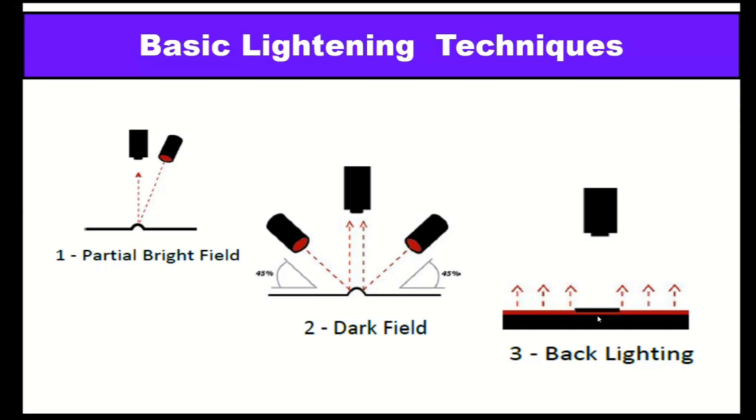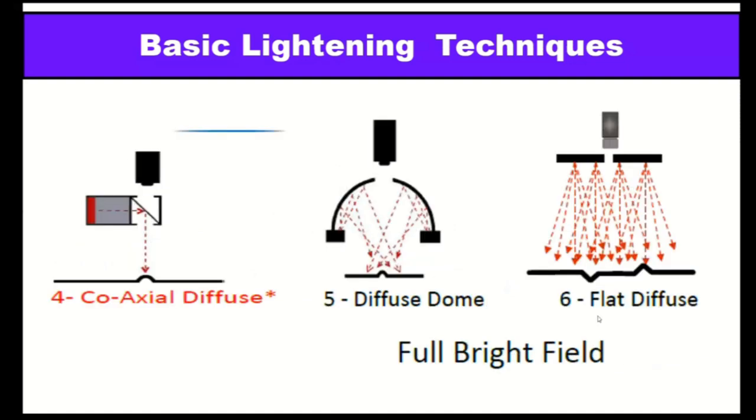Further, in case of transparency, if you have glass, plastic, or many other transparent things, then light can pass through the object. So the light source will be below the object, and you can capture the area correctly. Some special techniques are there where we need to align the light source correctly. So we can use reflectors, we can use other methods of light.